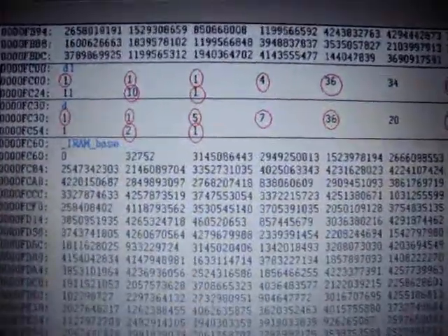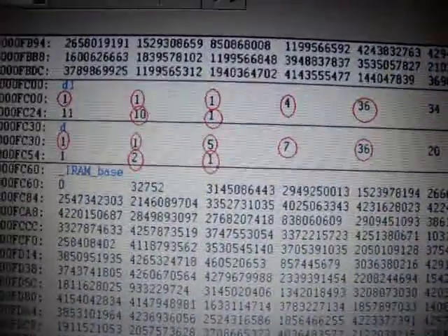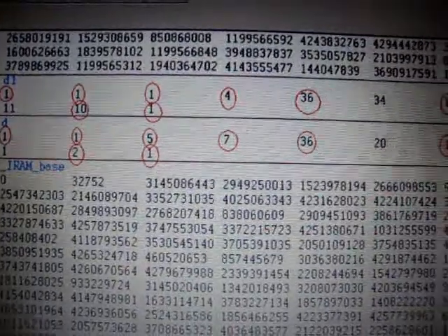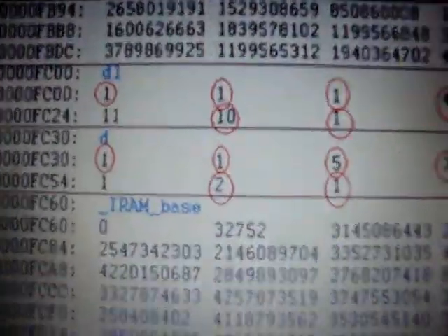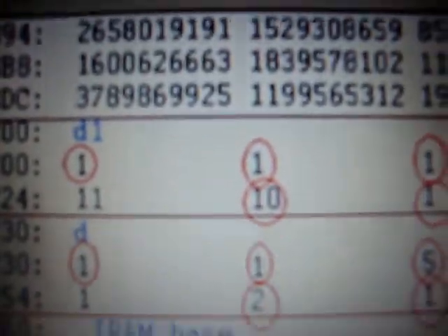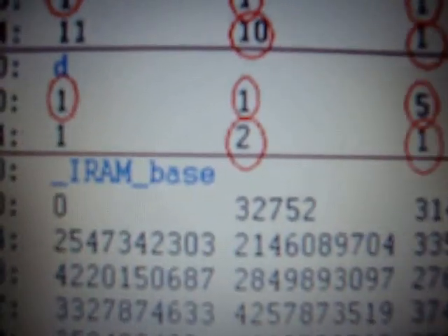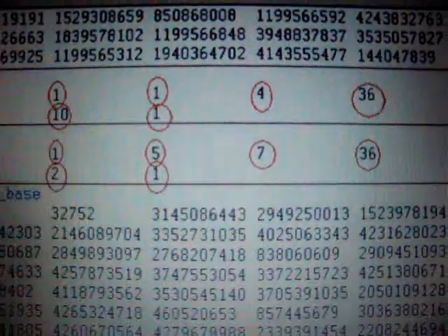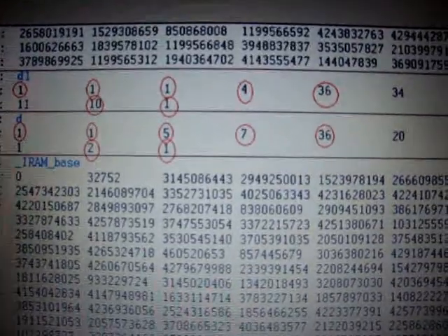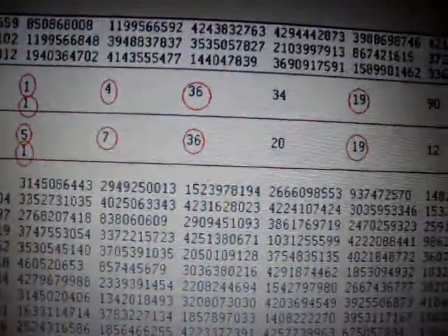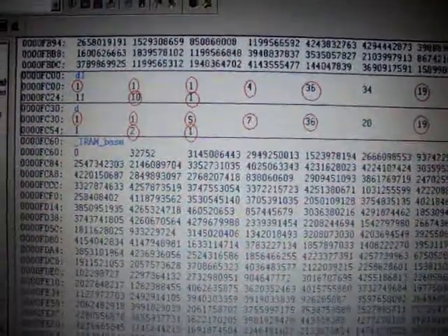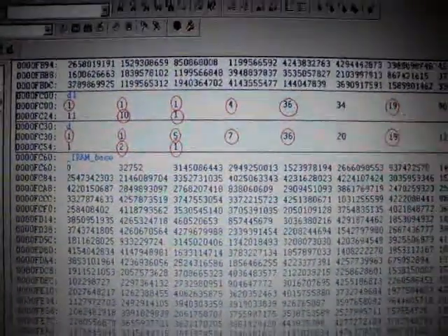Since the audio output through headphones cannot be shown on the video, we are showing you the values of the 12 feature vectors of both training and testing phase. D1 here represents vectors from the training phase, while D represents the vectors from the testing phase. If 7 or more vectors have a difference of less than 10 amongst them, it means both the signals are matched, else they're not. What you see now on the screen is for the matched word.